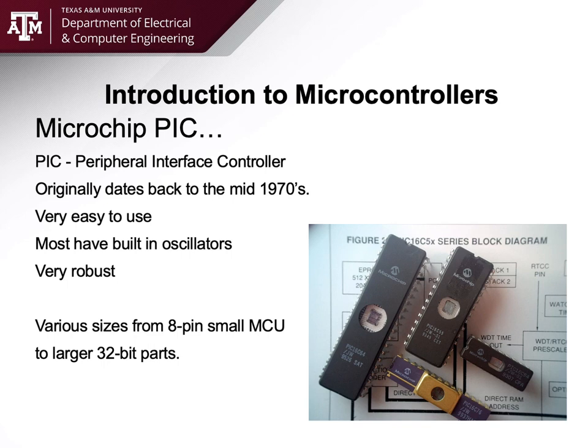They have expanded the family. They're not slow and sluggish like they used to be. A lot of the old chips are still available. They are very robust. I have used these in environments that you probably shouldn't be using a microcontroller, like heavy lightning prone environments. And we need a microcontroller, but it's like anything we toss out there is going to get zapped. These processors can usually handle that punishment. Don't know what is different about them, but these older Microchip PICs can pretty much take a pretty brutal beating electrostatically and also just in the environment.